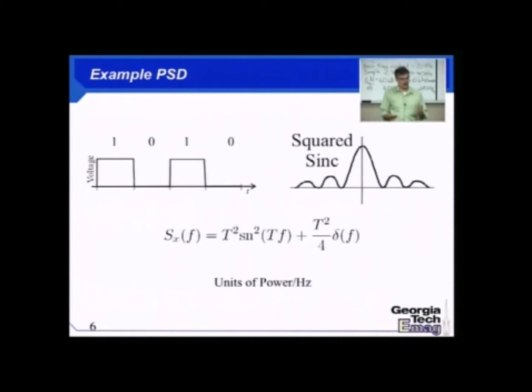But one of the problems is I'm going to go to 0 at either end of that symbol period, and I'm going to stay at 0, which means the support of my pulse, there's that word again that we learned in antenna engineering, the support of my pulse is only 1 symbol period, nothing more. That automatically means I'm going to have some high-frequency energy.